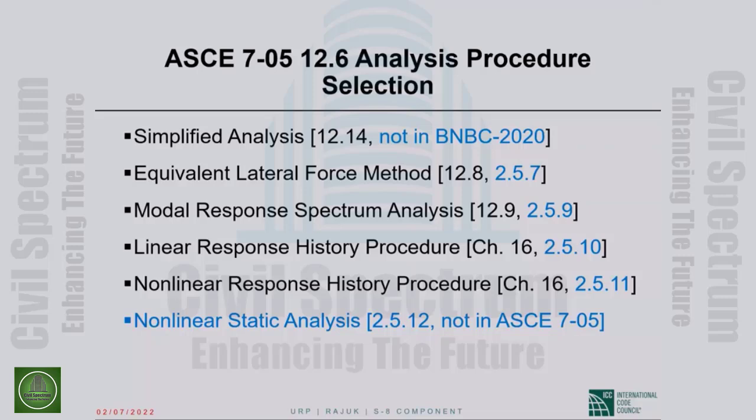In the second case of nonlinear time history analysis, we recognize reality and concede that certain regions of certain structural members will go inelastic in the earthquake ground motion that we are analyzing for.